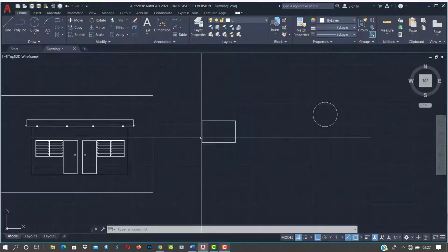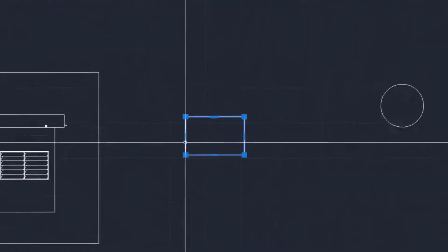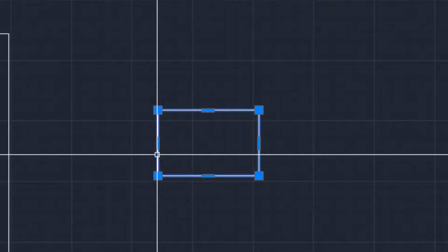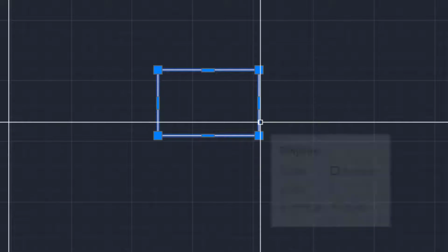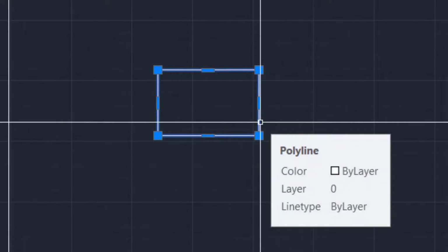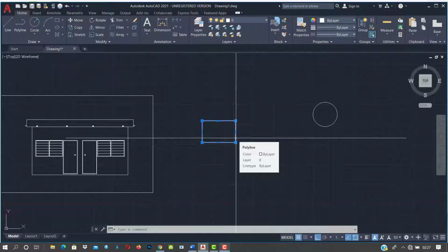So let's say if I have a box over here, maybe in my section, and I want to create several series of them, but in reduced or enlarged scales. Instead of using the scale to do it manually, you can just use the offset tool with a constant offset distance to create series of the same object without going through that stress. So let's just get into it.